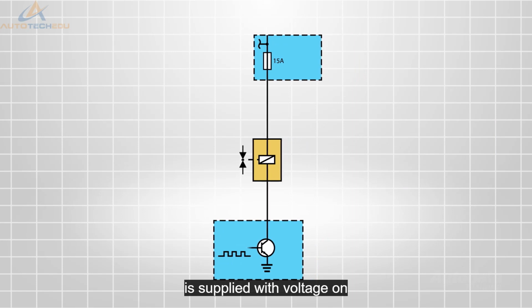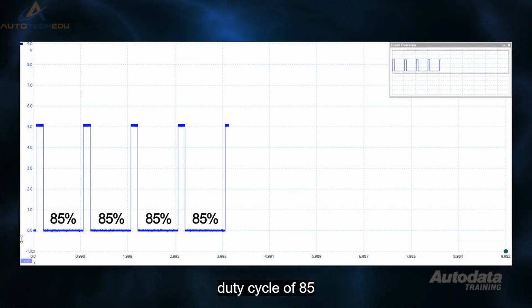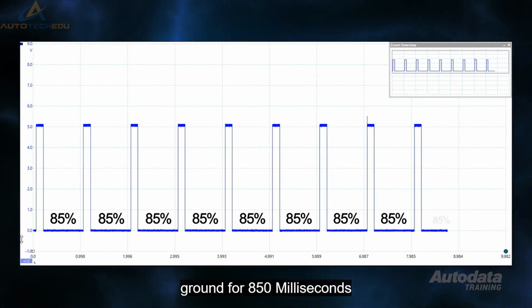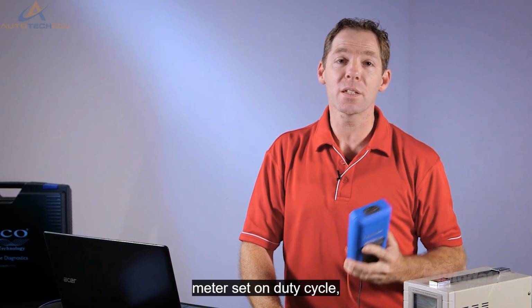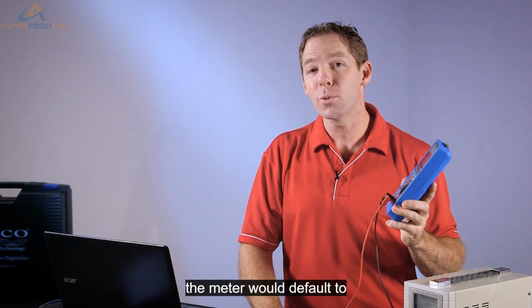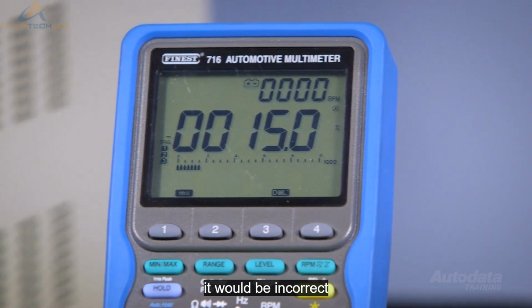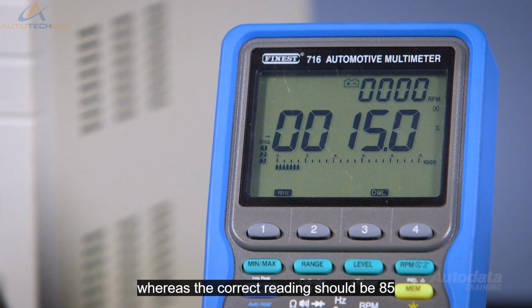This solenoid is supplied with voltage on one side and is pulled to ground by the control module on the other. This trace has a negative duty cycle of 85%. The solenoid is pulled to ground for 850 milliseconds. If I was to measure this control with a multimeter set on duty cycle, the meter would default to a positive reading. Unfortunately, it would be incorrect. The meter would display 15%, whereas the correct reading should be 85% duty cycle.